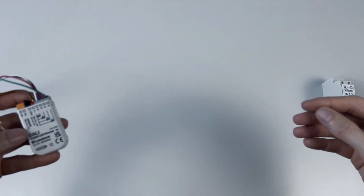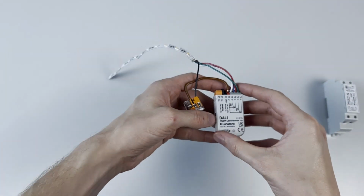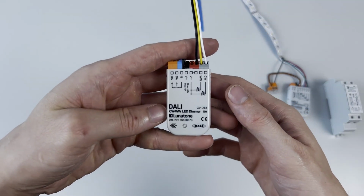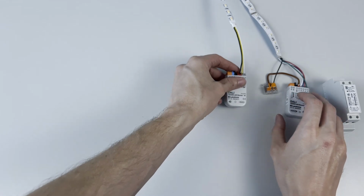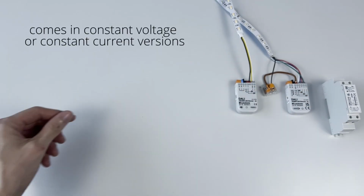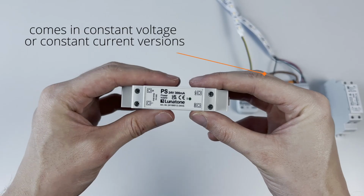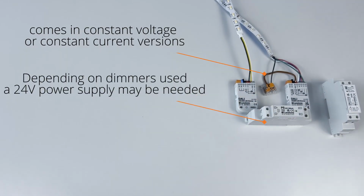2. Light sources. In our example office, we will use DALI dimmers connected to LEDs. Dimmers need to be chosen depending on the light sources. Different dimmers are available, for example, constant current LED or constant voltage LED. Depending on the dimmers used, you may need a power supply that provides 24 volts to the dimmer.